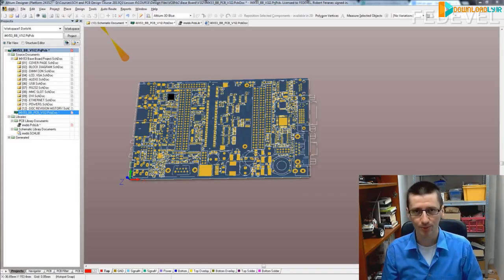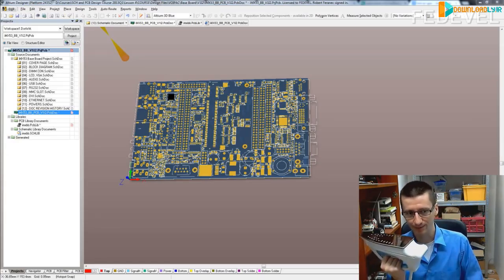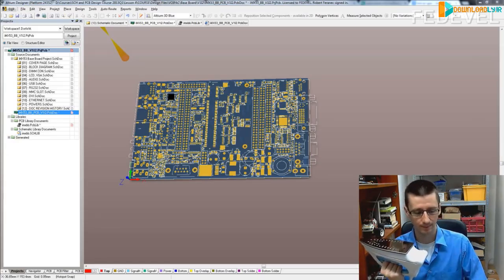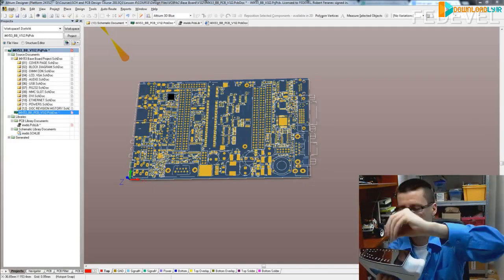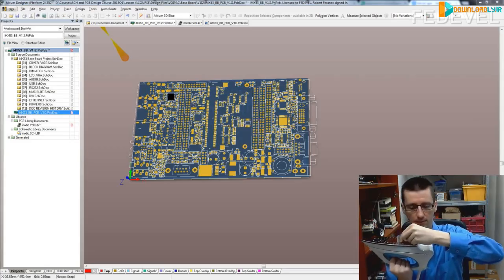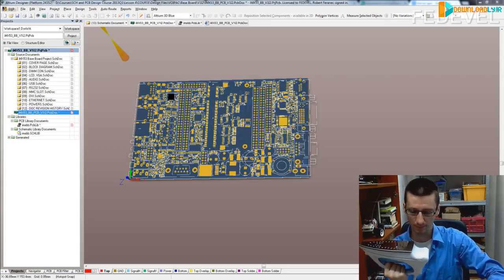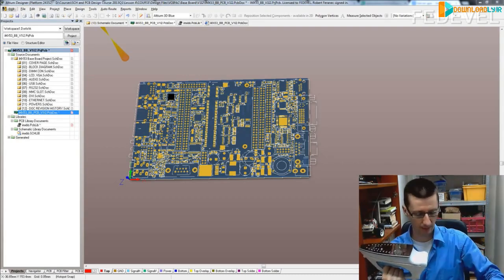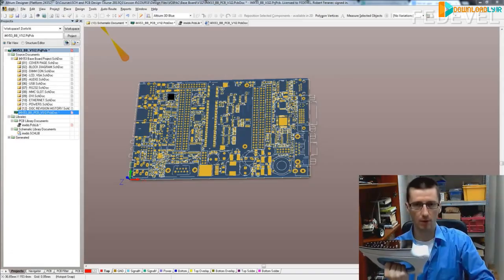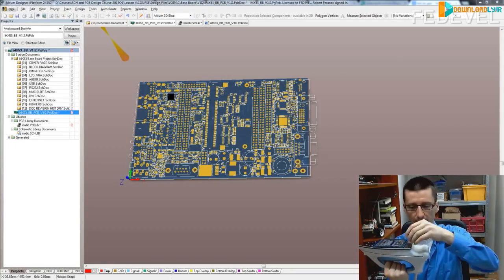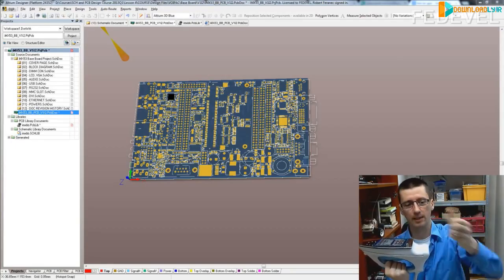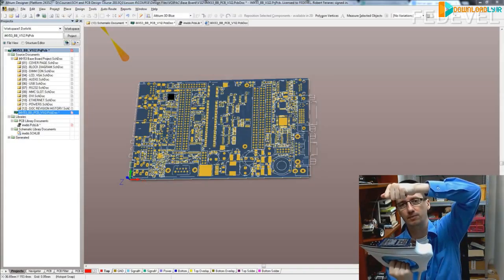What we used to do, we had an iron and we placed small nuts on the iron, like this, and then we put our PCB on the top and big nuts around and another iron on the top.